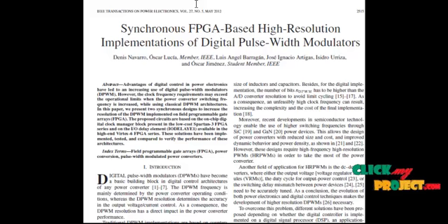However, digital control design also has disadvantages. The two most important are processing and sampling delay, and limited resolution. Resolution is limited mainly by the analog to digital converter and the pulse width modulator. The ADC is becoming a less important problem thanks to the windowed ADC technique, whereas the pulse width modulation resolution needs to be higher than the ADC resolution to avoid limit cycles.